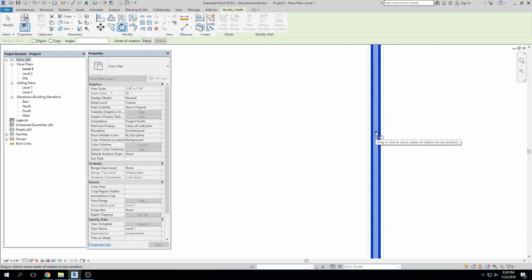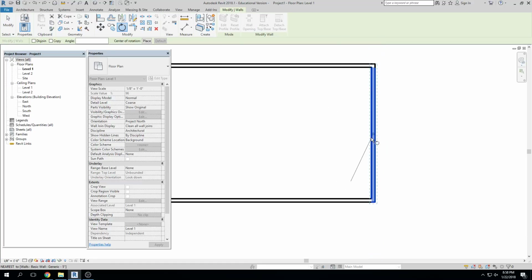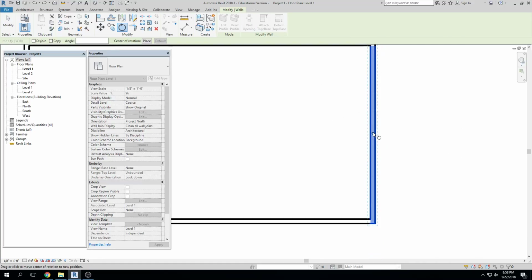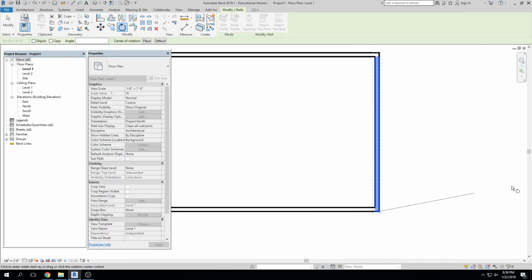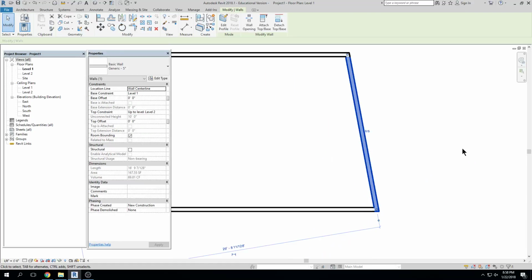And I don't really like where that rotated that wall. I don't like that it rotated it right in the middle. So I'm going to click on it, it's that blue grip, hold my mouse button down, and move it somewhere else. And I'm going to let go, right? So I can change how that wall is rotating. I can click my reference plane, move my object the direction I want it to go, and I could type in 10 degrees, enter, right? What does it say? It's like can't keep elements joined. Oh, so you have something that's trying to break apart from another thing. Yeah.